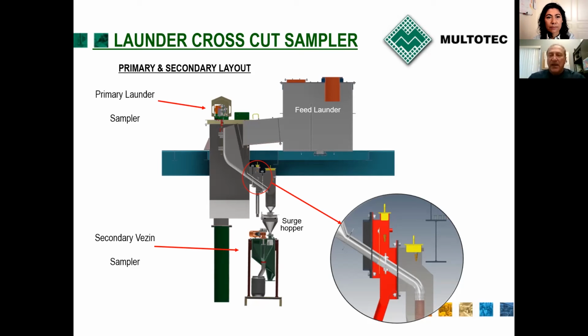Depending on your flow rate, which might be too high, you would collect 6 liters instead of 2. Therefore, to still be representative, you do a cut of the primary sampler into a secondary sampler, which is a second cut of the first cut. That lowers the quantity you recover, but it is still reliable.